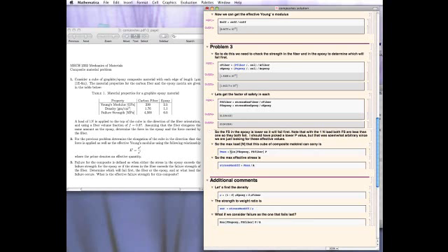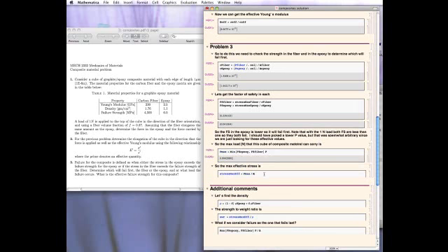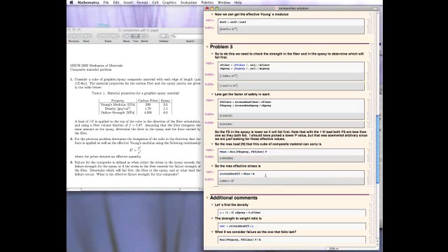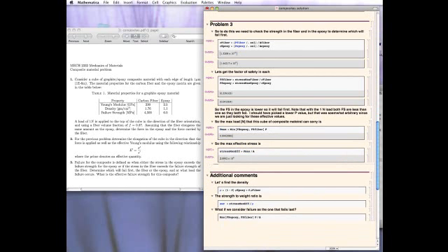So all we're doing here is scaling the actual force by whichever factor of safety is less. And then likewise here, we get the max stress as this maximum force applied over the cross-sectional area. And so here you can see the maximum stress allowed is this 200 megapascals. Okay, so that becomes the strength of the epoxy.